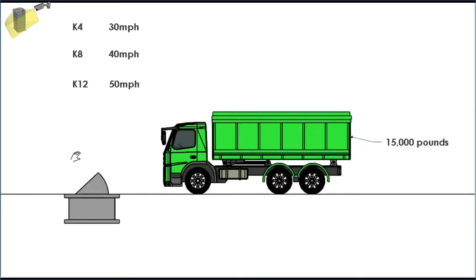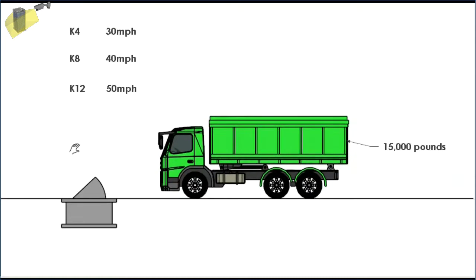The American Department of Defense has standards for road blockers. These are crash ratings K4, K8 and K12. We're assuming that a vehicle which weighs about 15,000 pounds is going to hit the road blocker.